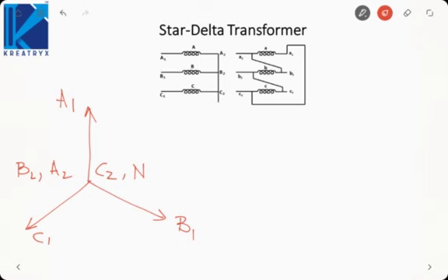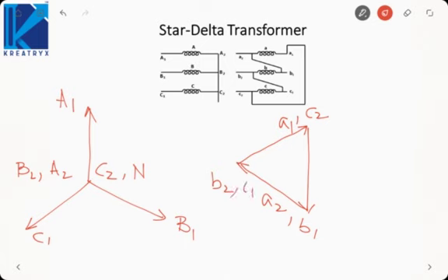First, we are taking the output at A2, B2 and C2. So let us draw A1 to A2. A1 to A2 will be vertically downwards. Now A2 is connected to B1. So B1 to B2, how it will be? B1 to B2 will be like this. Now B2 is connected to C1. C1 to C2 will be like this. Now since we are taking output at A2, B2 and C2, we must remove the 1 subscripts.